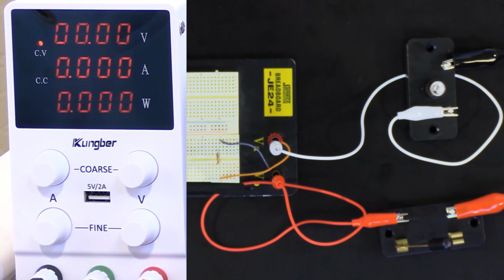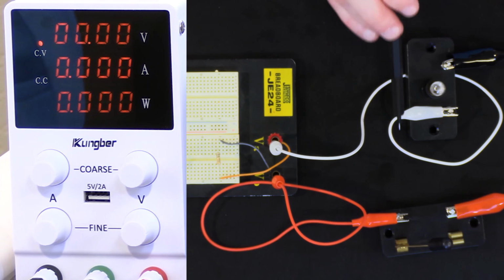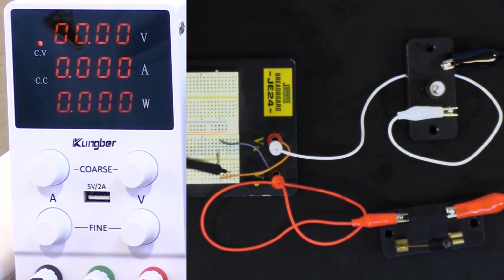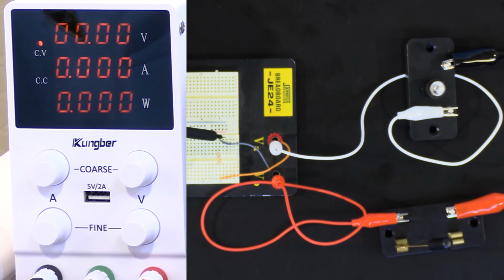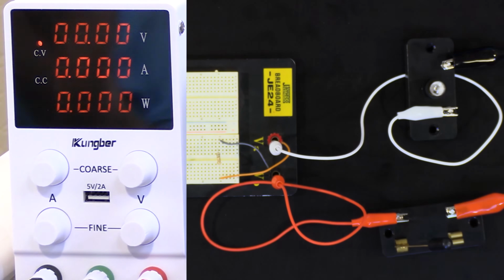So what's really happening is the electricity is coming here, going through the light bulb to the white wire, and then it's going in here, connected underneath to this point, then it travels through the resistance, and then through the gray wire into the red, and then through the switch, and then back there.